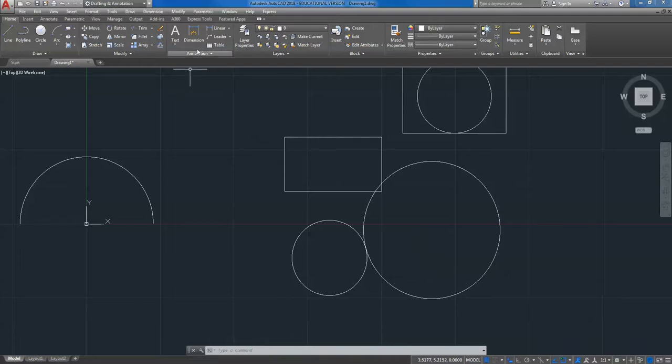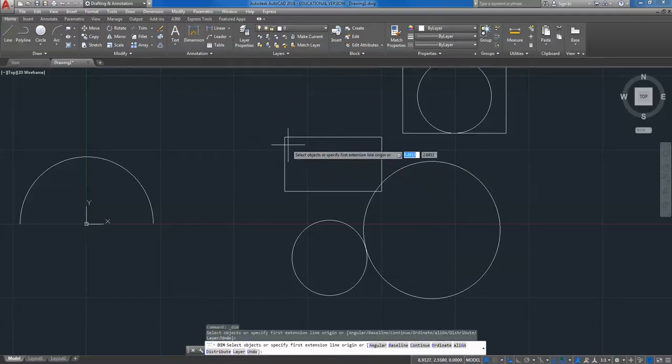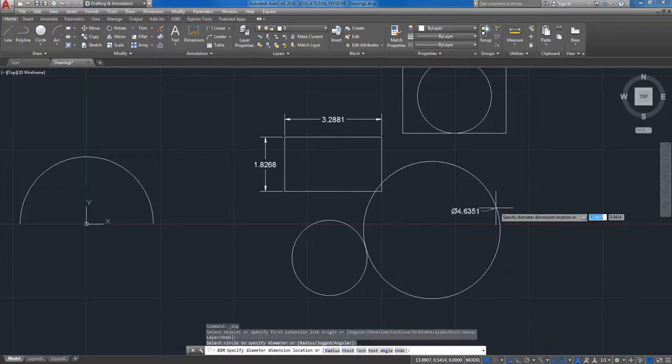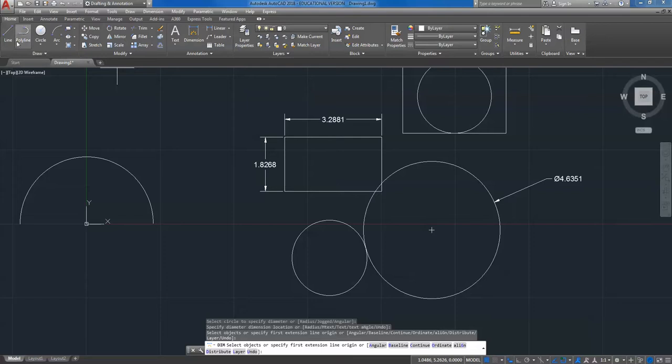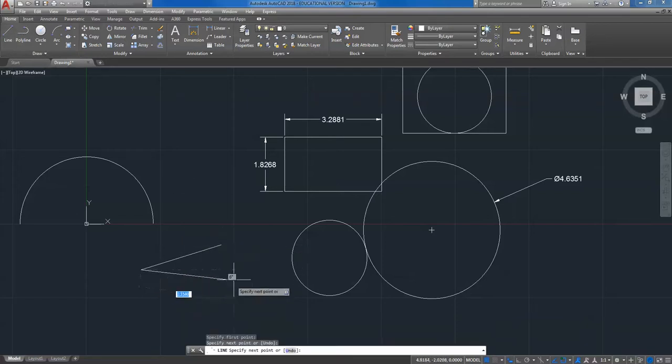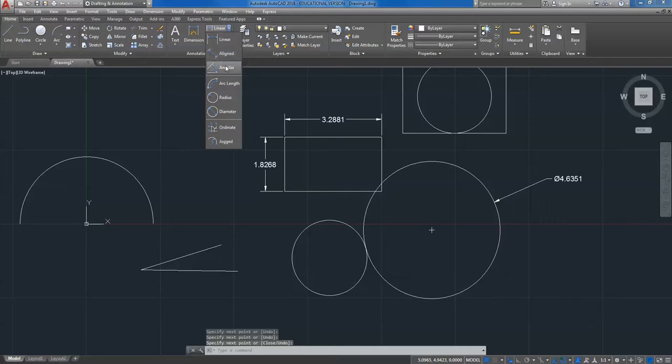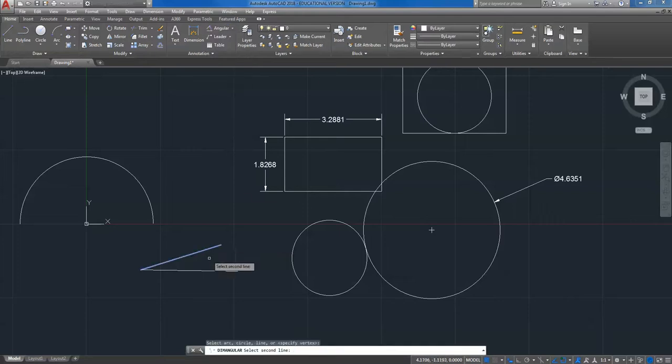Just really quickly, if you're going to be doing dimensioning, just to double check, you want to dimension this arc as well, okay? Sometimes you'll have lines and you'll want to dimension an angular line, or an angle, I'm sorry. You click on those two there and create an angle. All right, so for chapter 4, what you'll do is go ahead and build all of the parts up to part number 10, okay?